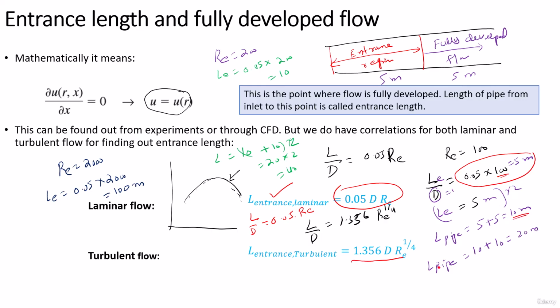The remaining length of the pipe can be any length, 10 meters, 20 meters, 30 meters, but I chose 10 plus 30, 40 meters. L by D is equal to 5, so if I take the diameter equal to 1, the entrance region is 1 times 5. So I doubled it to 10 meters and added 30 meters more.